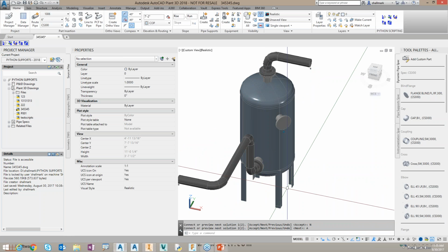Like that. I see another question has come in. Can we modify the equipment on Inventor and reinsert it in the model? You would still have to export out to ADSK. If I'm understanding the question correctly, if you're also using Inventor to generate or design equipment, you're still going to need to export that out to ADSK to bring it into Plant.